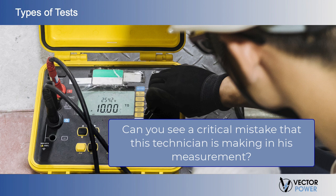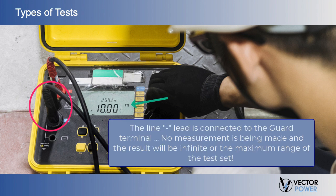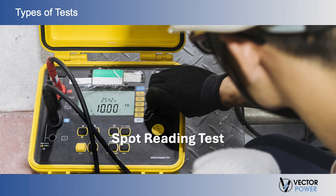The reading can then be compared to the minimum installation specifications. Spot readings can be performed as part of an inspection or as part of troubleshooting and can be used as a simple good-bad indicator. Spot test readings can also be trended against previously obtained values. However, insulation resistance is highly temperature dependent, and thus the results should be corrected to a standard temperature.